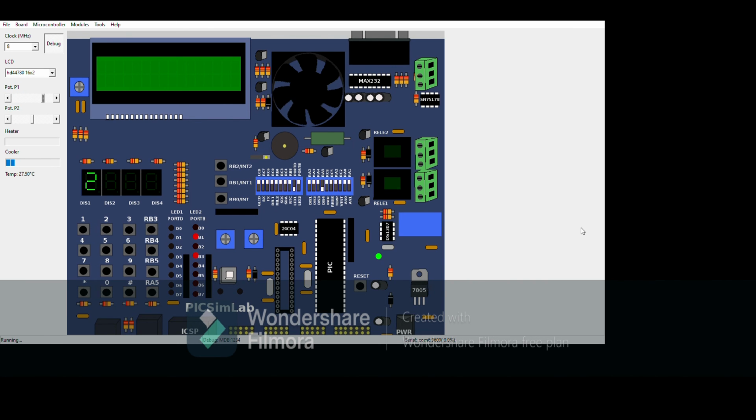And now this is the result for the second state and third state. When the potentiometer is within the range of 1 volt or less than 1 volt, the display will show 2, and 2 LEDs will light up, which is the LED that we simulated during the first state, and another LED that we use in the second state. So now I'm tuning the potentiometer.